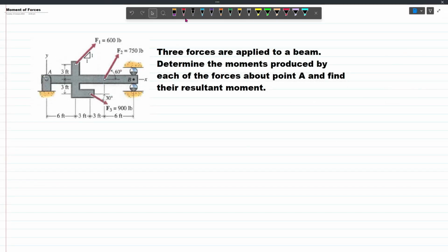And so now, we'll try to solve this problem. Now this will be easy because we already discussed all the concepts. Now first, we will resolve these inclined forces into components. Now recall that if you have a force P and then this is, let's say, a 3, 4, 5 triangle, if you want to get the x component, you have Px is equal to P times the actual x component divided by the hypotenuse. And then if you want to get Py, you have P multiplied by the y component, which is 4 divided by 5. And so this is how you get the components.